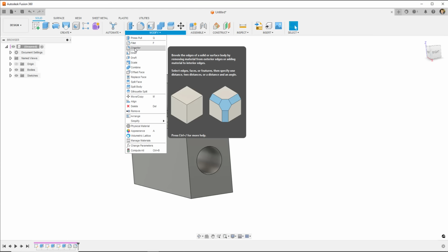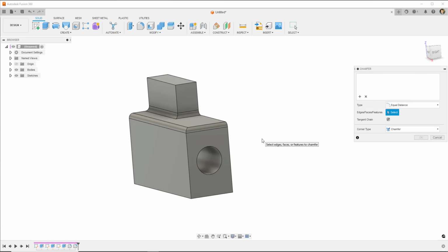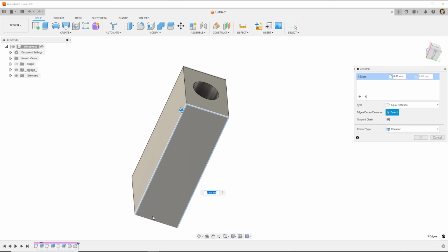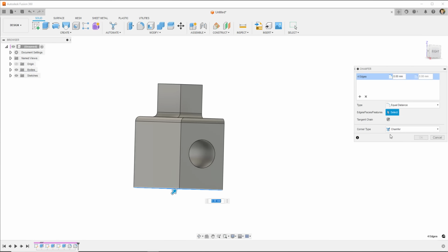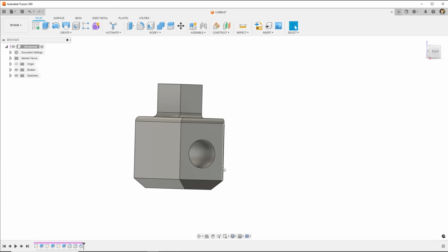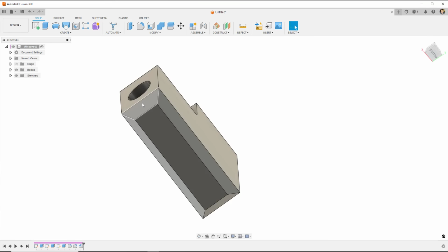And you could even use it. Well, let's do a chamfer this time, which works exactly the same way, but I'm going to chamfer the bottom edge. Oops. I'm going to deselect that. I'm going to chamfer this bottom edge all the way around. And it's going to be an equal distance chamfer, so you could tell it to, if it wasn't 45 degree, equal distance basically means 45 degrees, think of it that way. Or you could have different angles, different distances. We'll keep it simple. Let's go with 10 millimeters. Okay. So now it's got a bit of a chamfer there.